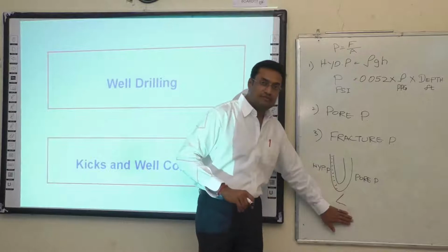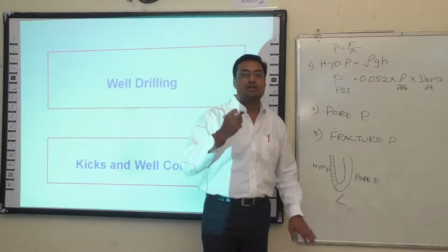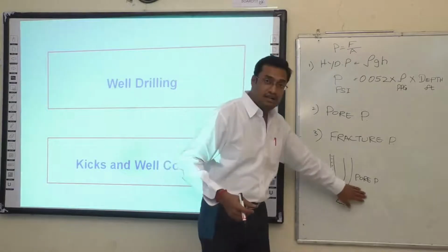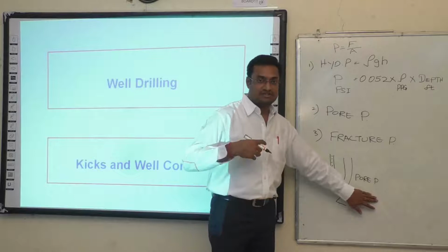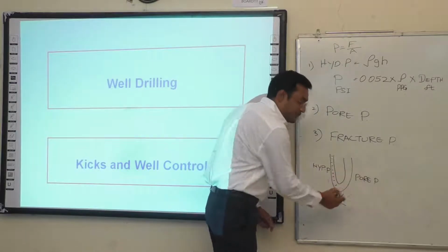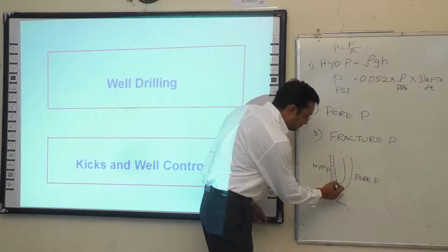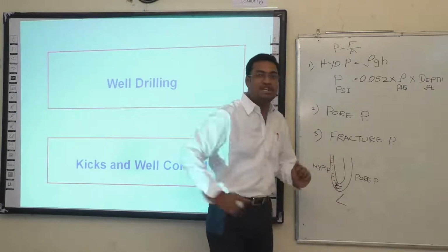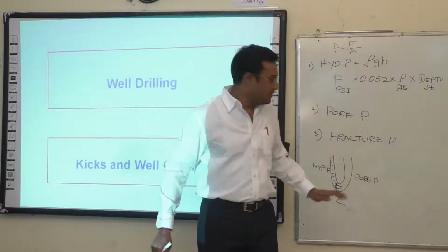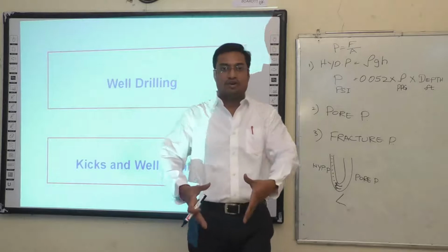If it's an underbalanced condition, we start losing control over the well, and the well takes control of us. So the pore fluids start coming inside the wellbore, and it disturbs the wellbore. Where we maintain the drilling fluids, we give hydrostatic pressure to control.